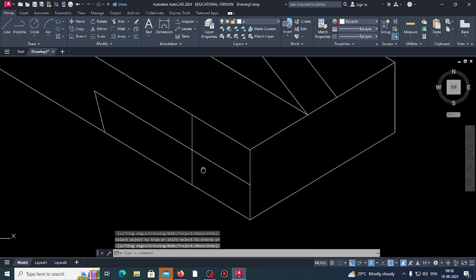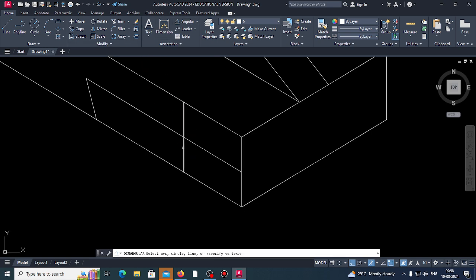Okay. Now coming to this, let us measure the angle of the vertical line with this line. It is 120. It should become 45. So 120 minus 75, this side 75. It will rotate this side. Plus 75, minus 75, negative value, it will rotate this side. Okay. Now rotate. Select object. Enter. Base point. About this point we are going to rotate. Minus 75. Okay. Now trim.